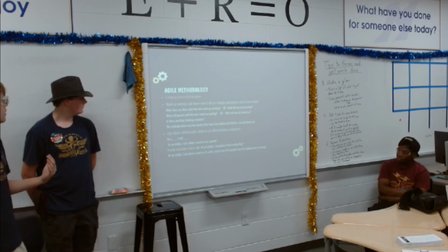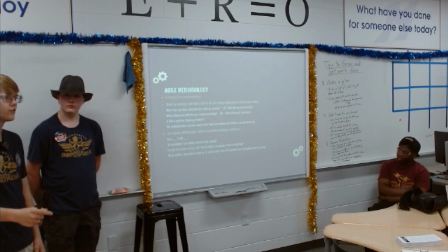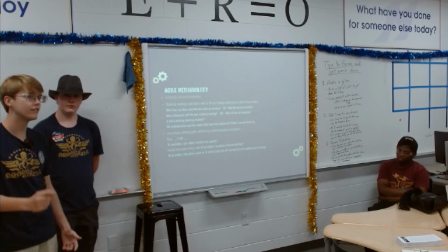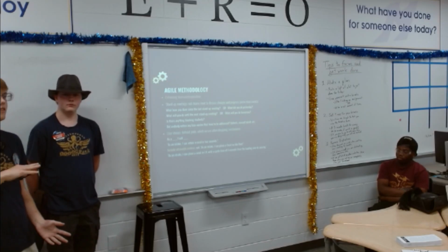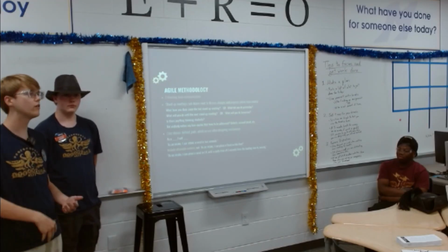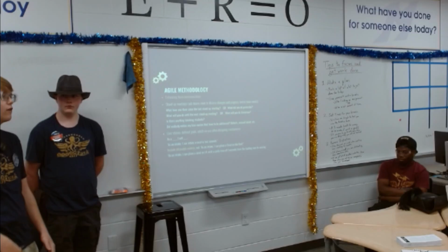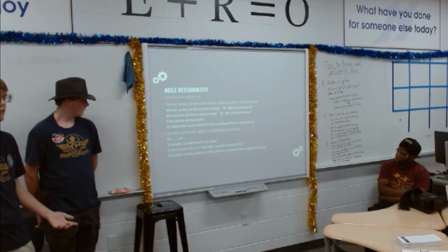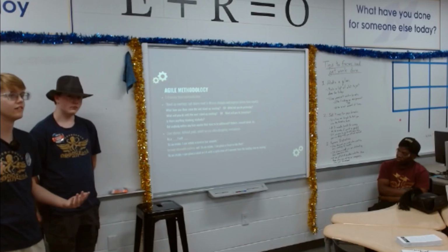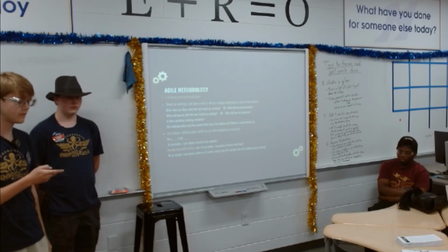And then a big part of user stories is that it has definable metrics. It's not like "is fast" or "is tall." It's not random, subjective adjectives, but something that's definable. So I want the lift to extend 90 inches from the robot frame. Or I want the intake to intake a coral in 2 seconds. Or I want to score 4 points in auto, something like that.